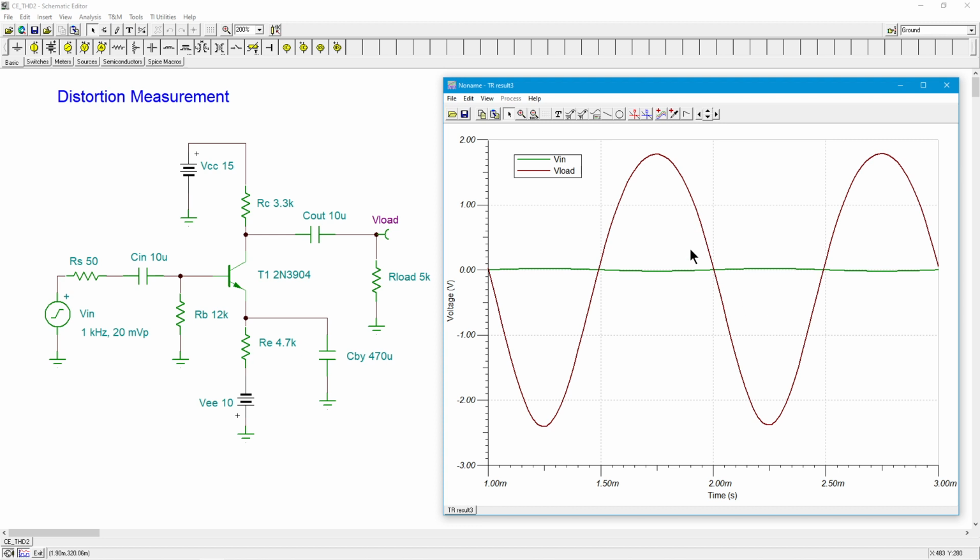Because this does not have half-wave symmetry, there's got to be at least one even in here. There's got to be at least a 2K or a 4K or a 6K. I don't know where it is. Probably there's going to be more than that. There's maybe a little bit of 2K and some 4K and so on, along with odd harmonics as well.